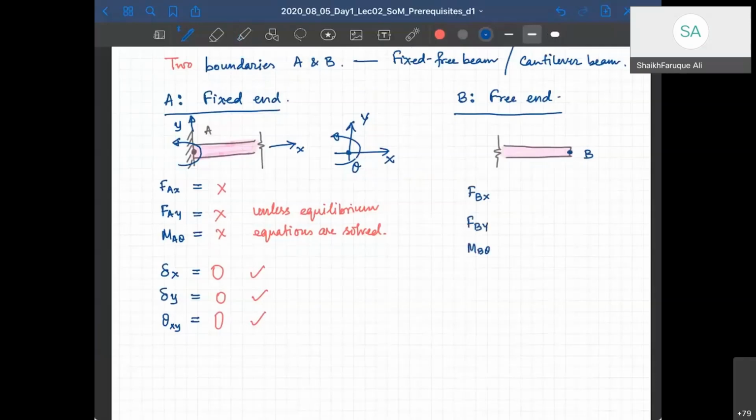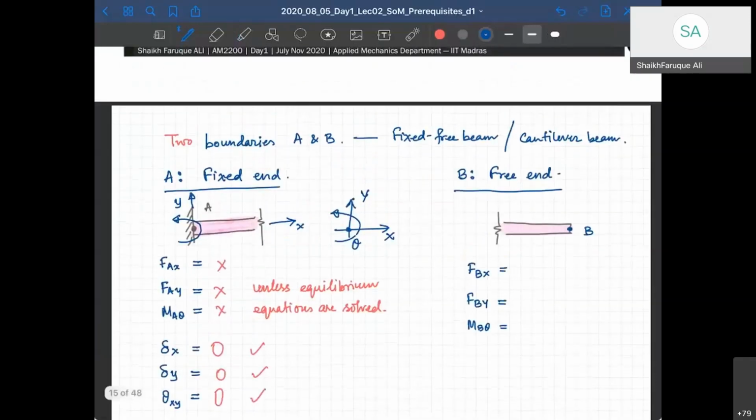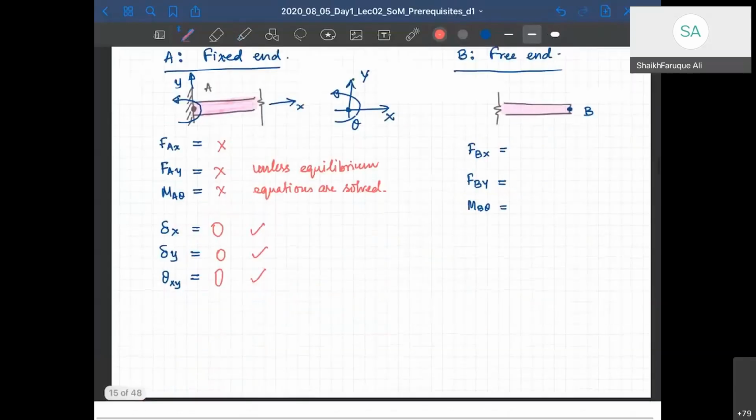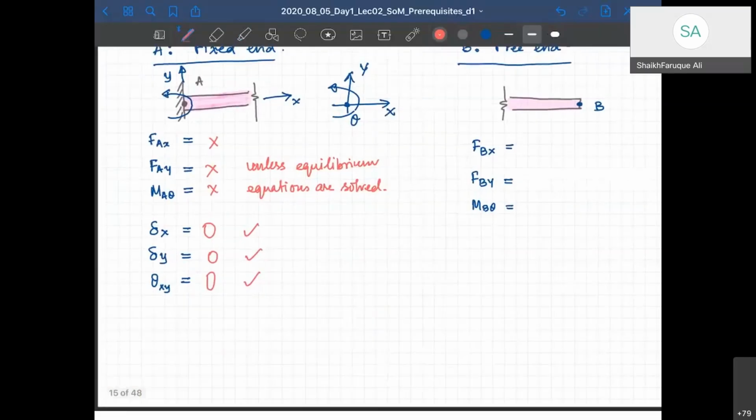So these are the forces I have, and we are looking at a planar body, not a 3D body, so a planar body in plane. When looking at an in-plane system, I have only 3 unknown forces: Fx, Fy, and M. For a 3D object, it will be Fx, Fy, Fz, and Mx, My, Mz, 6 of them. Here it is 3 only.